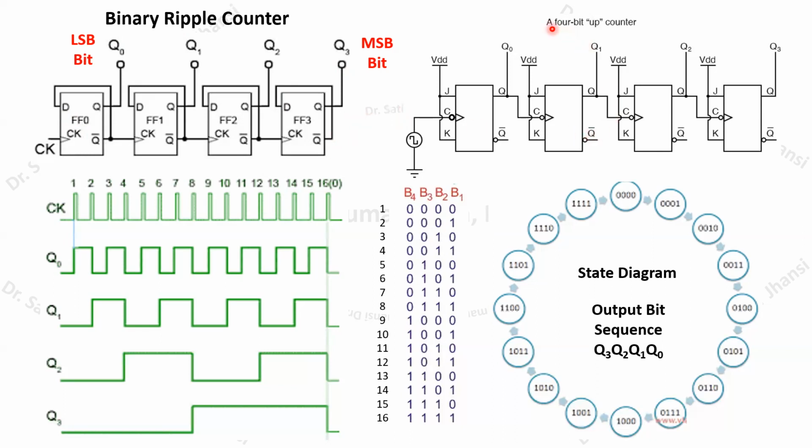Here again you can see this circuit, using this JK flip-flop. So the same circuit you can also implement by having the JK flip-flop. So binary ripple counter using the JK flip-flop you can make, and here we are using this particular negative edge triggered flip-flop. So that way you have to make this circuit, and then you will be able to observe the output. You remember that the JK flip-flop should be in the toggle mode. That you have to remember.